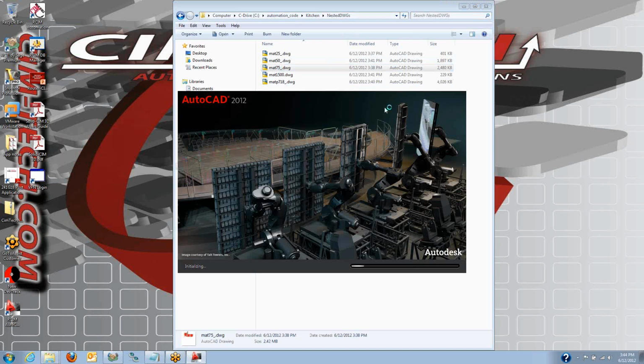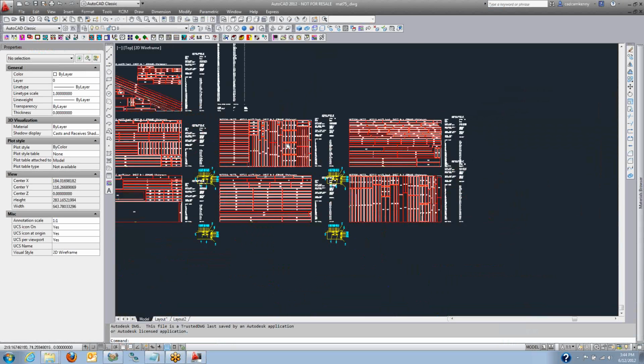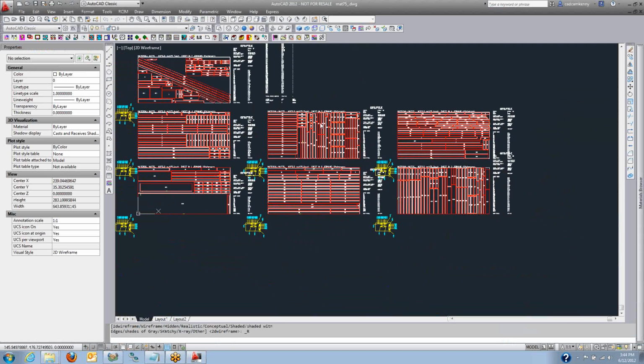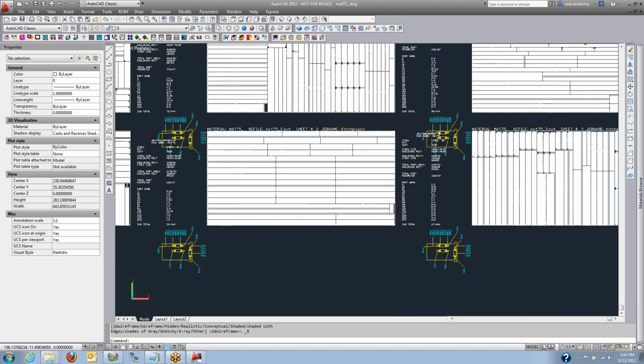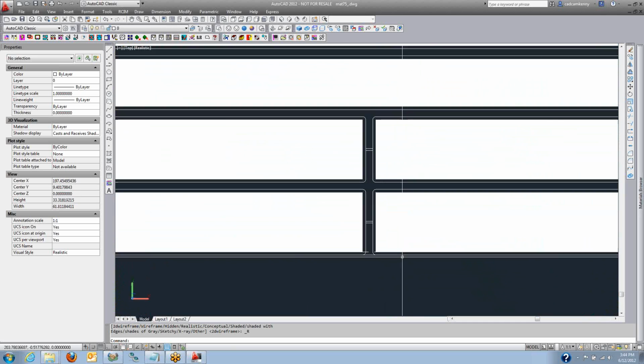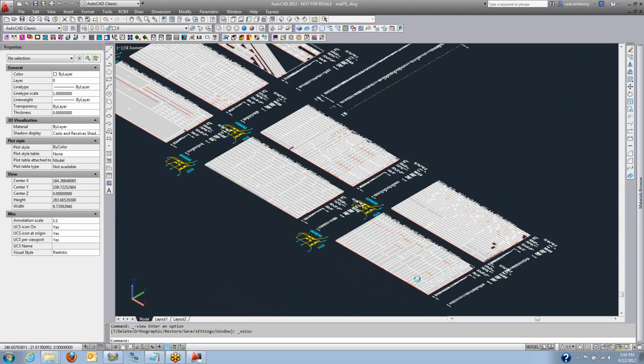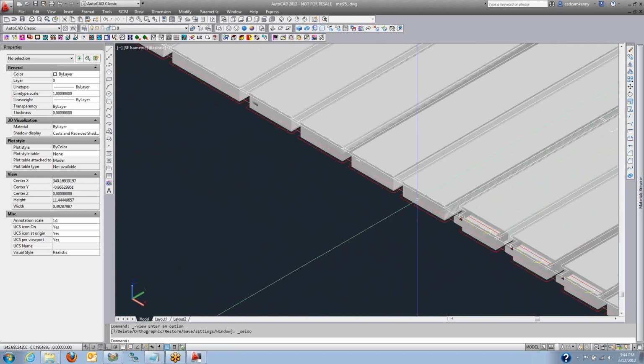So you can open the drawing files and you can make changes to the nests. You can resequence those, make new NC code if you like. There's our full nested sheets. You could see with the shading turned on, the rendering turned on, you could see the individual 3D solids. And here's our stay down toolpath built into each one of these toolpaths. We've got a stay down nest where the tool stays down and connects from part to part without lifting up.